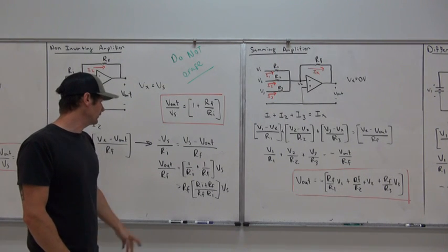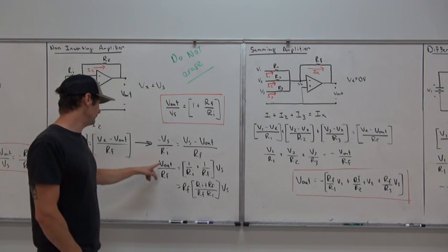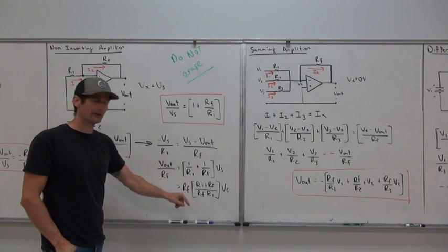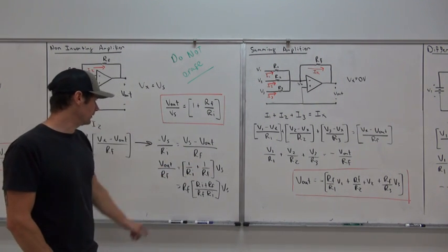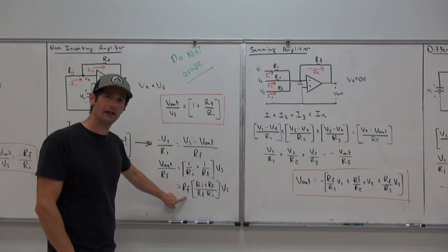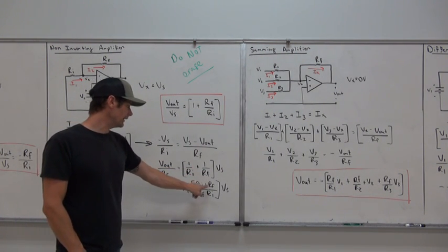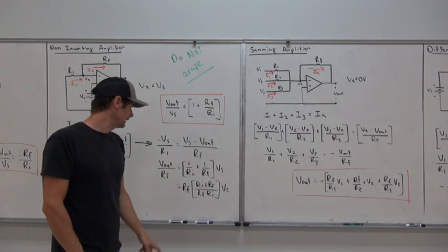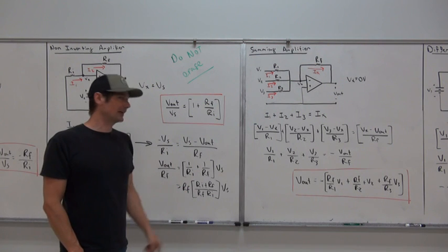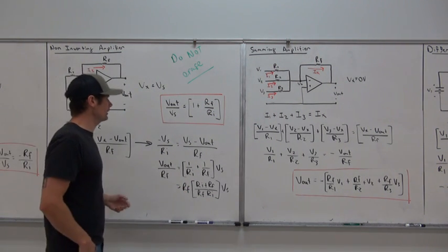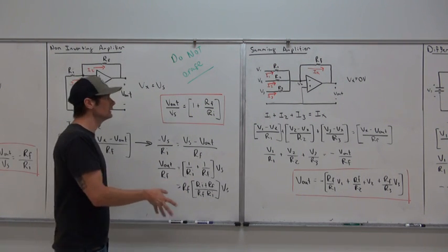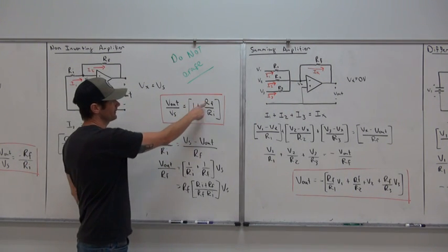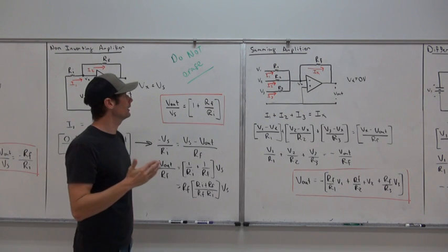If we rearrange the equation, we get Vout over Rf equal to 1 over Ri plus 1 over Rf times Vs. We simplify, so we get Rf plus Ri over Rf times Ri equal to Vs. The Rfs cancel each other out, and when we rearrange the equation a little bit, we find that the gain for a non-inverting amplifier is equal to 1 plus Rf over Ri.